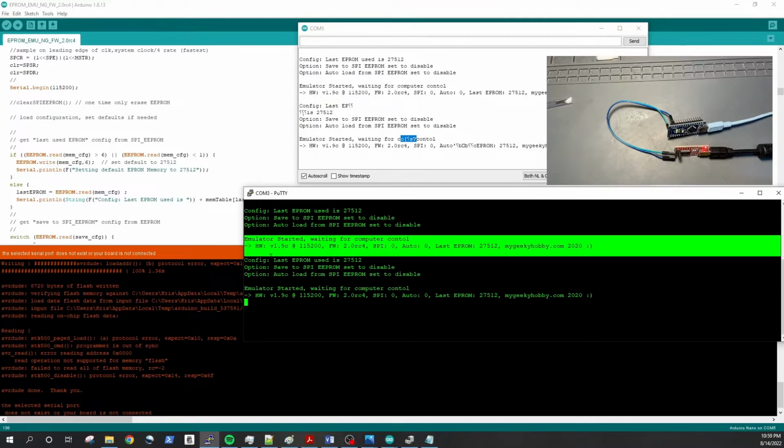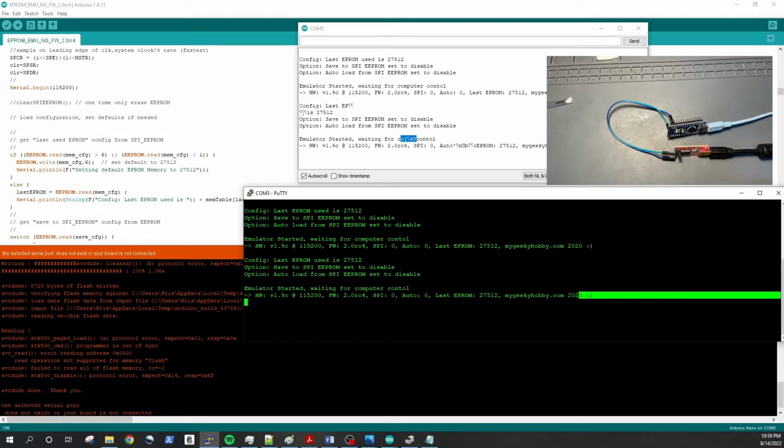But on our second copy, on our other TTL to USB converter, we don't see those messed up characters. So that confirms that the problem is indeed that CH340 that is built into this Arduino that is causing the problem. I've seen it before. I've replaced quite a few of those CH340 chips, because occasionally I come across exactly this problem.